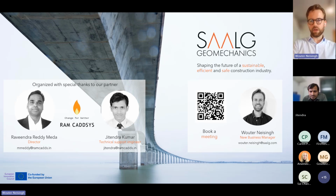So we could basically conclude, okay, in the first 1 or 2 phases, we see a certain pattern. Then we know that for the next 6, 7, 8 phases, we're also going to expect this behavior. And therefore, thanks to the Daarwin BackAnalysis, we are able to optimize this into a more optimal construction method that allowed us to conclude that one of those temporary props is not necessary to be placed because the soil conditions are better. So in this case, that's one of the techniques that we used: early on in the excavation, doing extra tests and then getting that information to improve your design along the way.